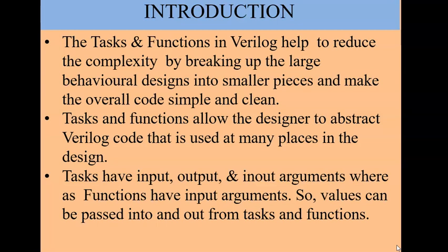Tasks and functions allow the designer to abstract the Verilog code that is used at many places, as I have just now told you, many places in the design. Tasks have input, output and in-out arguments, whereas functions have input arguments only. So values can be passed into and out from tasks and functions. This is the most important.